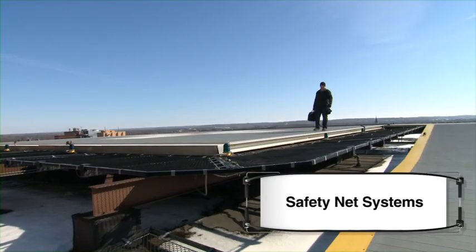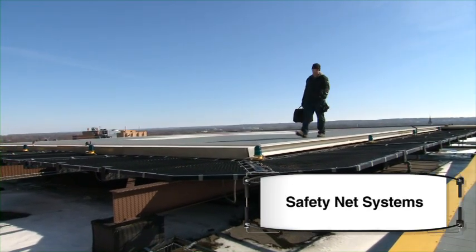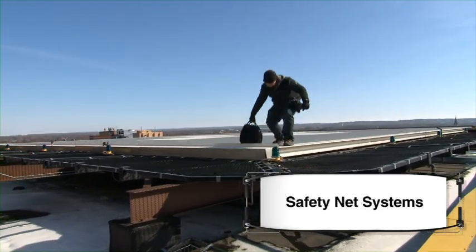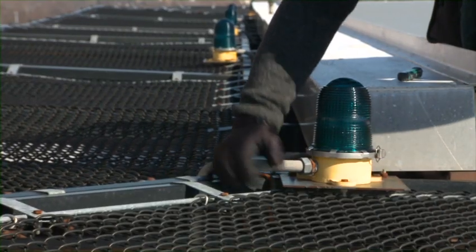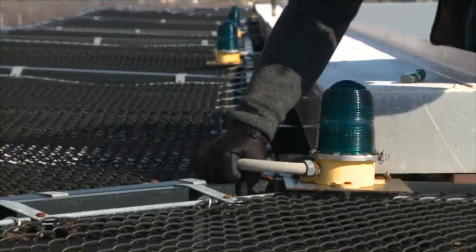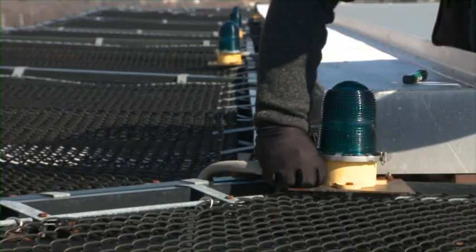A safety net system is a horizontal or semi-horizontal cantilever-style barrier that uses a netting system to stop falling workers before they make contact with a lower level or obstruction. Safety net systems are used for protection at unprotected sides when working on roofs and around openings.